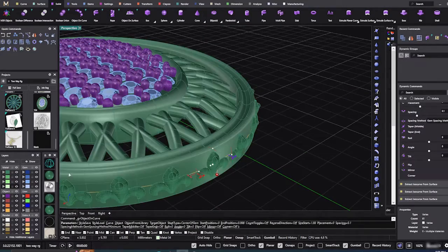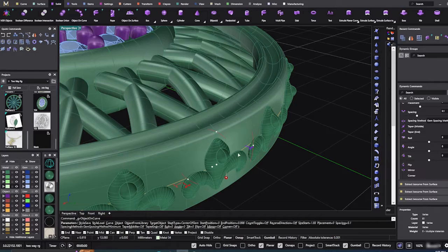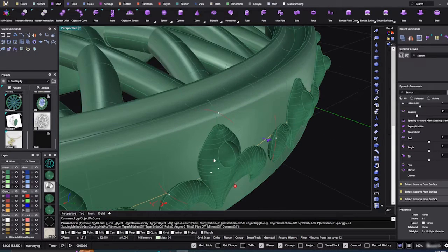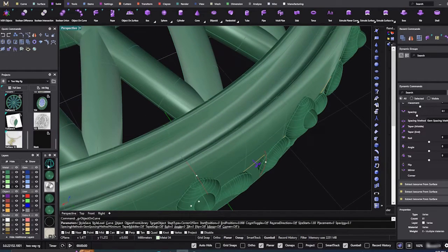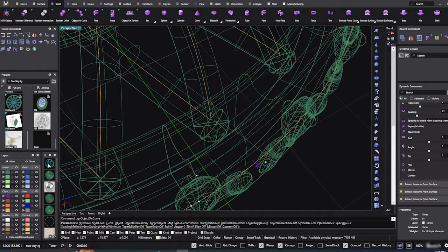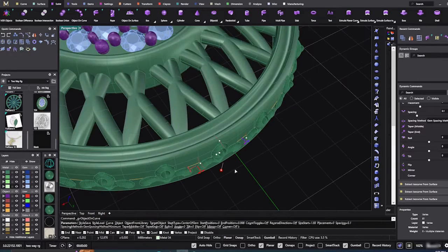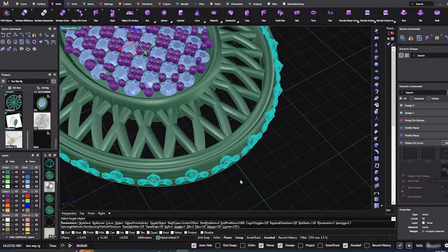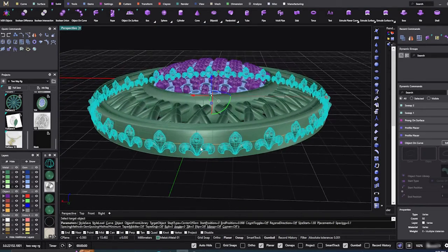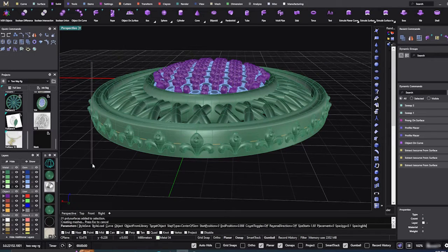So let's go back here, and I want to drag. It's pretty close. Let's go to wireframe. Take a look. Okay, they're okay. So what we're going to do is say enter, enter, and it places them out there, right? But instead of Boolean join, we're going to do a Boolean difference. Okay. So it'll cut them out, leave a cutout there. So we'll go to a Boolean difference.